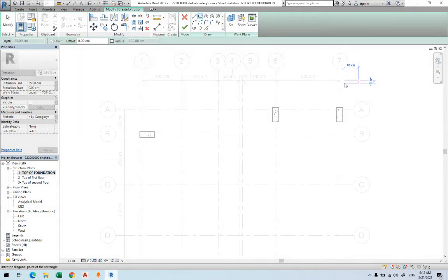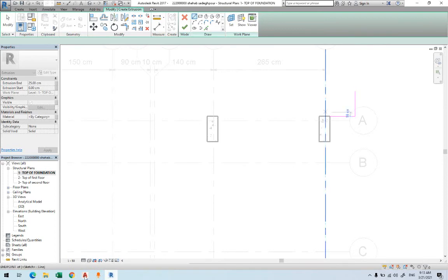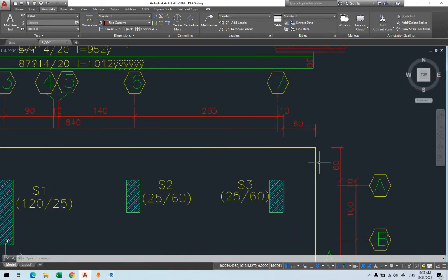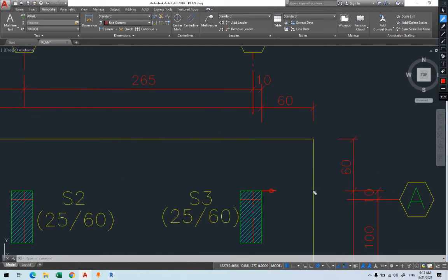Well, in order to start, first I will draw some lines. Later I will delete them. Let's say I know from this corner I have to go one click, 60 centimeters. Then I will go up 60 centimeters. What I'm doing is finding the starting point. This is the starting point, the corner which I showed you here. I know that it is 60 centimeters from here and 60 in the other direction. So this corner I have it. Look, I drew a line in order to find its location, and later I can delete those lines.